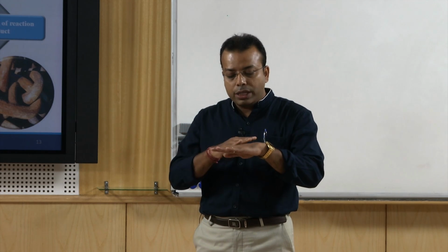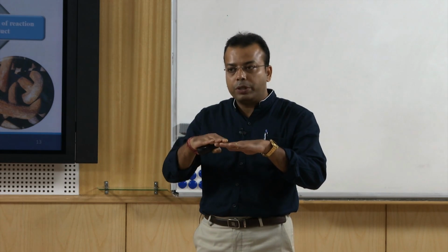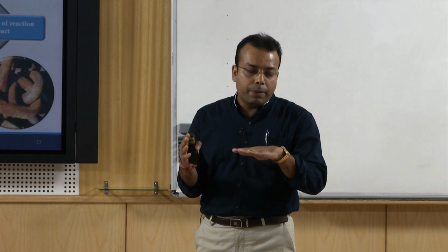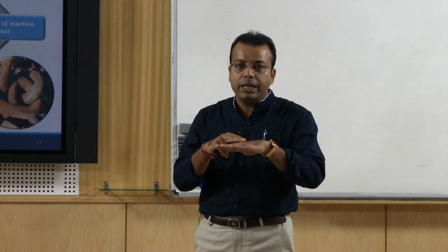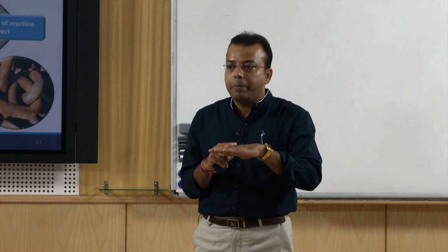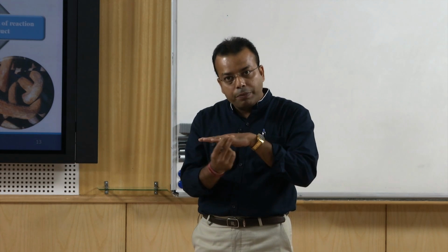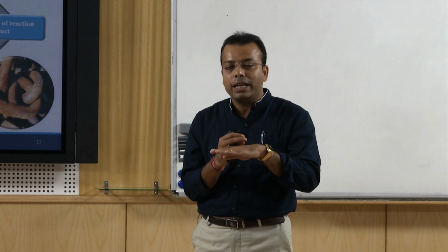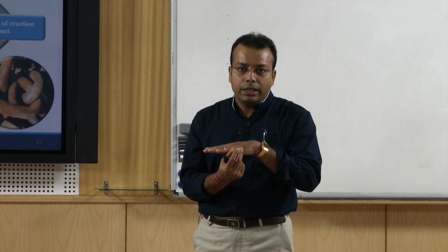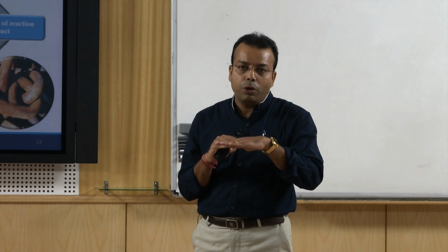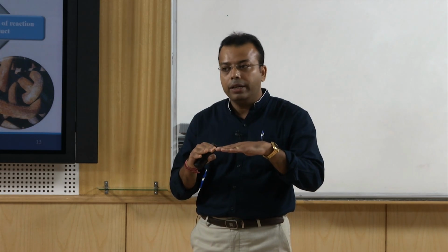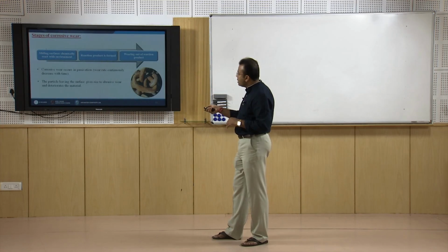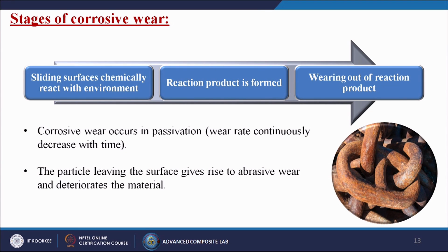But after corrosion, when some kind of oxide formation or sulphide formation has taken place, there is no virgin area which can react with the environment. That oxide or sulphide film will act as a barrier layer between the environment and your material. So, over time your corrosion rate will decrease. The particles leaving the surface give rise to abrasive wear and deteriorate the material.